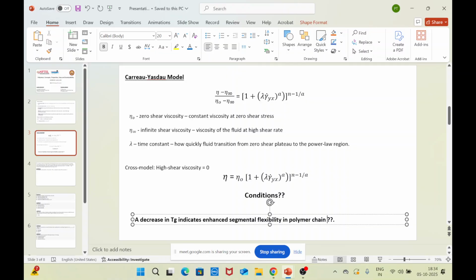Since the conformational disorderness decreases, the conformational entropy also decreases. And this we have learned before itself. So if the polymer chain stretches, an internal stress gets generated, which limits the amount of solvent that enters inside the polymer, and that prevents the swelling. Usually an equilibrium is reached between the osmotic pressure and the stress that gets generated inside the polymer matrix.